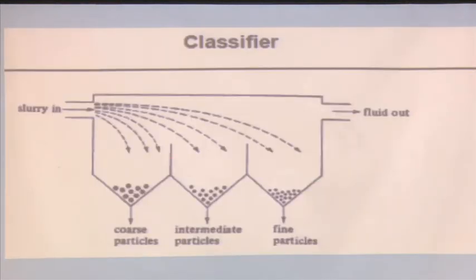Next one, that is what we discussed in the introductory one also. Now, I can know that the slurry is coming. So, if I know the settling velocity of my particles, then I know that this particle will settle here, and up to what distance it can be carried. If I know a little bit of fluid flow problem also, that we have not discussed, then I know what will be the dimension of this, what will be the width of this, based on the range of particles I want to have segregated.